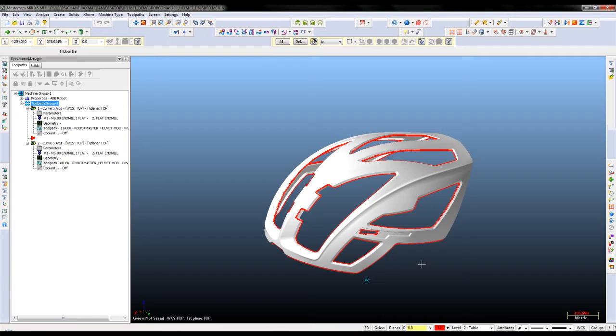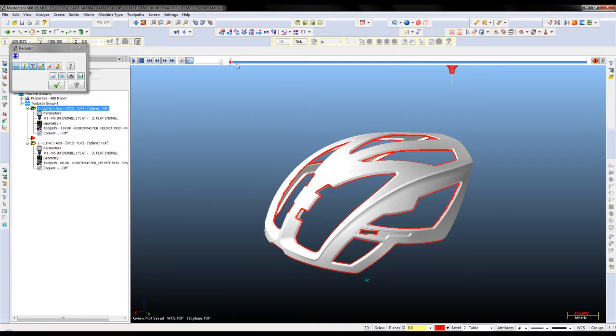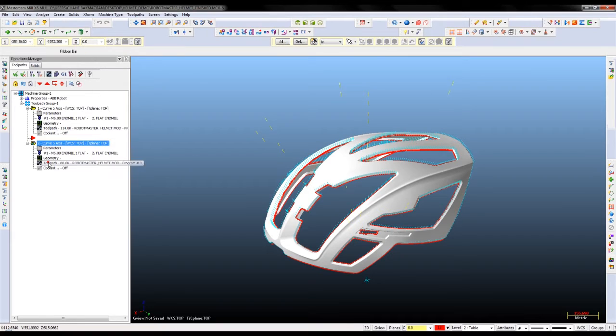So the first step is you bring in the CAD model. This is the CAD model, and this is the part that we want to trim. The first thing that we do is we have a way of automatically detecting all the edges that need to be trimmed or welded and generate the paths. So we see here with one click of a button, we're able to determine all the areas that need to be cut, and we can create paths for those.